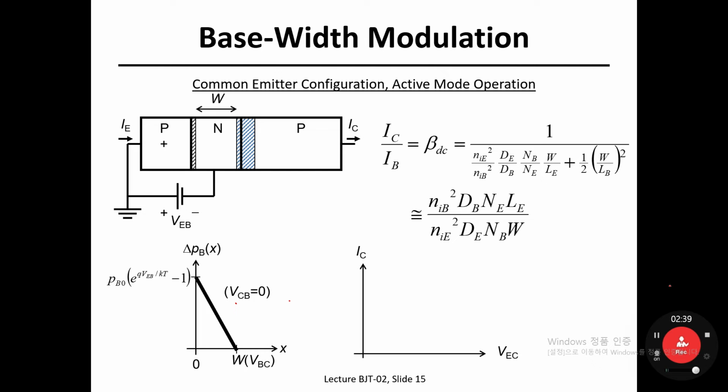So going back to the issue in BJT, what is the corresponding or counterpart of short channel effect in BJT? Yeah, the answer is the title of this slide, base-width modulation. Okay, so since we are studying with PNP BJT transistor, and this transistor would be used maybe for analog circuit application, would be used as an amplifier, so the BJT should be under active mode.